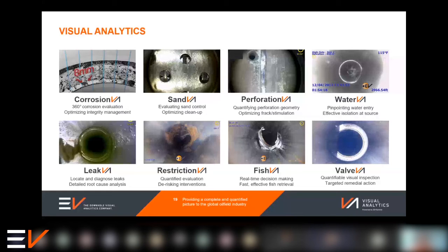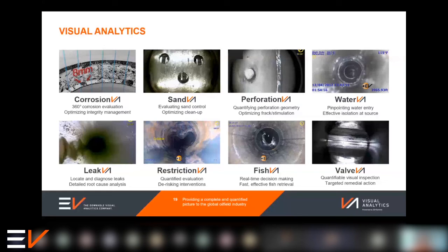But from my experience, when we're in a clear gas environment or a very, very transparent water, fresh water, for example, the camera can certainly see up to about 6 feet, depending on the ID of the well and the light reflection if we are approaching something with a metallic surface. So generally, we would certainly see very clearly within the 3 feet down to the 6 inches, but we can capture that.